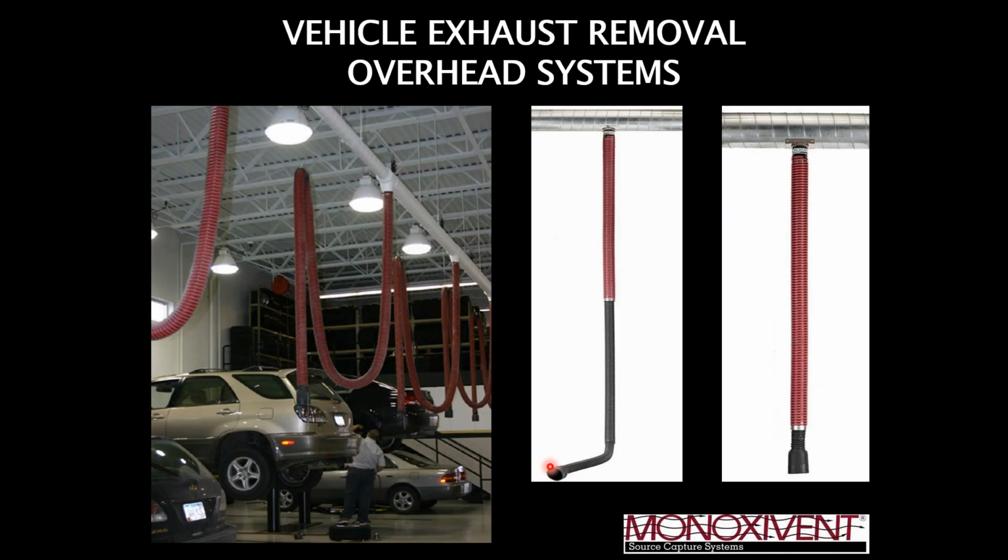All right. Next is what we call our overhead system. An overhead system works similarly to a hose reel in the sense that everything is up and off the floor, so you have a nice, safe, clean working environment. They're designed to capture 100% of what's conveyed through the tailpipe. Plus, we like to design it to capture another 20% of ambient air.